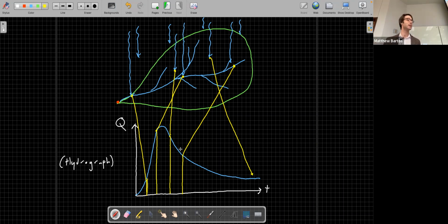So when you look at a hydrograph, what this is essentially is the distribution of all the different paths that water can take as it travels through the watershed. You can think of a hydrograph as essentially being the histogram of the travel times of the droplets of water as they land in the watershed. So it's important not only to understand where they're falling spatially in the watershed, but also how they're traveling, whether they're traveling through the channel or as overland flow or through the subsurface.